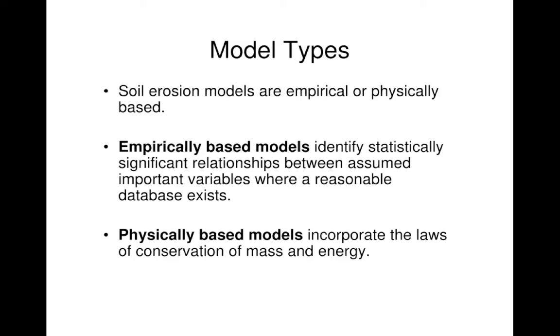And the third type, which I haven't really included, but is really interesting, and it's what used to be done a lot in the 50s and is starting to be done more and more now, again, are physical models. Now that's different from a physically based model. A physical model is you actually use a real soil of some type, and you apply water to that soil in a laboratory situation under controlled experimental conditions, and you look at how that's evolving over time. And you can learn bits and pieces about processes.